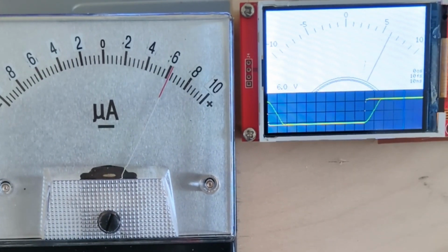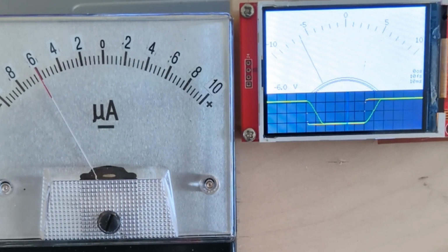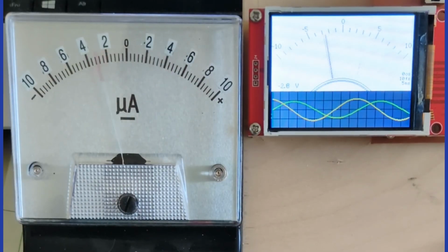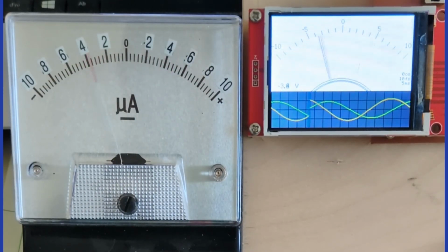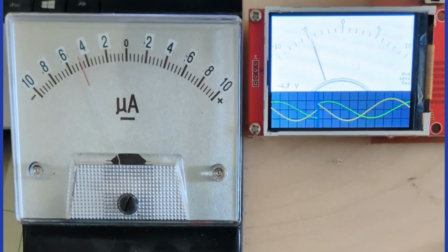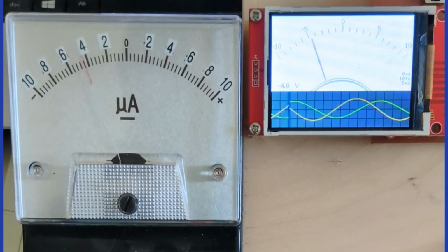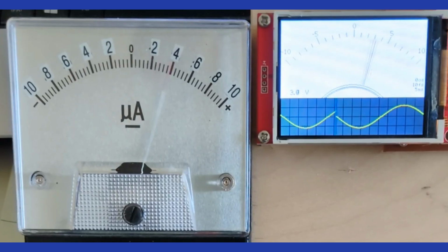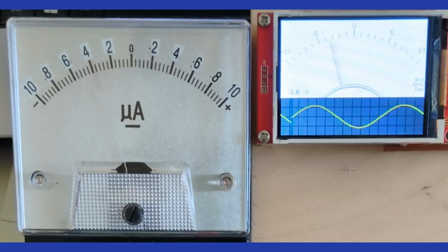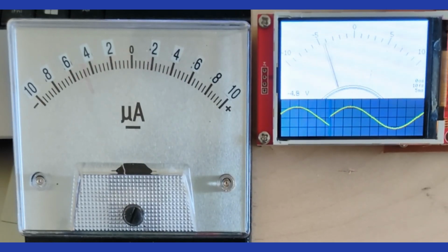A plus and minus 6 volt step response with PID control. A 1 Hz plus and minus 6 volt sine response without PID control. Note the phase lag and decreased amplitude. A 1 Hz plus and minus 6 volts sine response with PID control. There is good phase and amplitude matching.